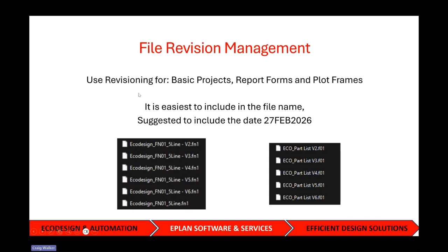If you've used Eplan for a while, you've no doubt created a report. So revisioning is good for reports, report forms. It's good for your basic projects, which are your template projects. It's good for your plot frames. And the easiest way to do this is just to simply add to the file name. And you can see examples here of what we've worked through the couple of years.